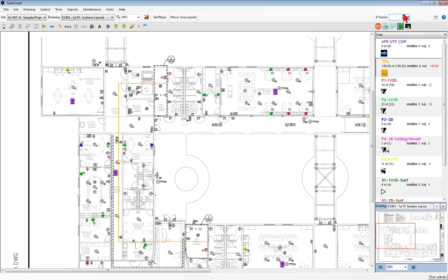I have a K-factor up here at the top that allows me to adjust or add for service loops or vertical rise or drop from this two-dimensional floor plan. So I could add 20 feet at the end of this cable at the horizontal cross-connect location and add an additional 20 feet by adding this K-factor in conjunction with this numeric constant here. And now I've compensated for that vertical rise and drop and service loop with a more usable connector-to-connector measurement of 191 feet here in the top right corner.